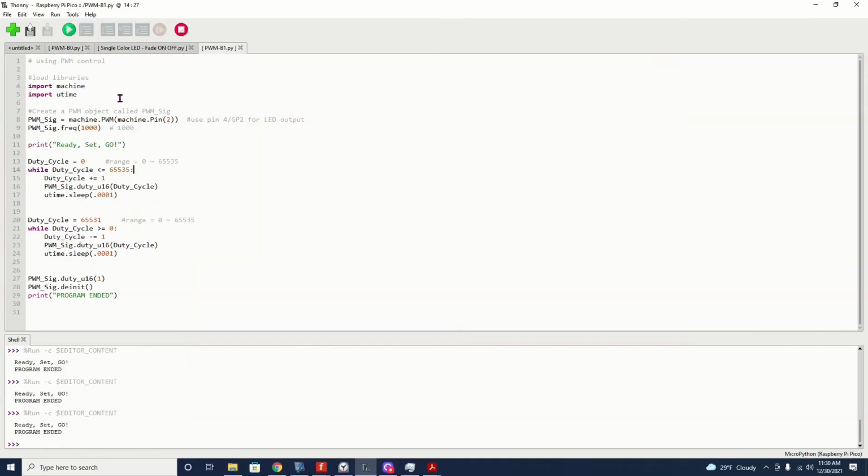Now, the last thing I want to show you with PWM, which adds a little pizzazz to it, and gives you that true variable speed control. What we're going to do with this example program is ramp up the brightness of the LED and then dim it back down slowly so that we can accelerate a motor and decelerate a motor, if you see what I'm getting at. And of course, these ramp up and ramp down effects can be pretty neat for various lighting situations as well.